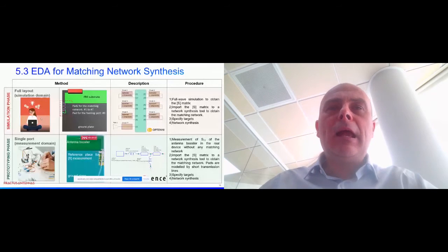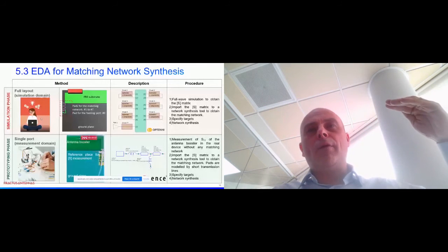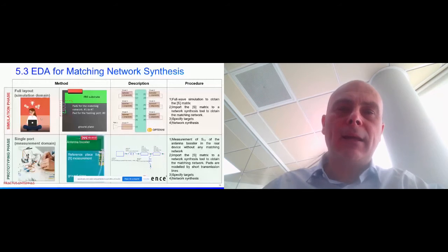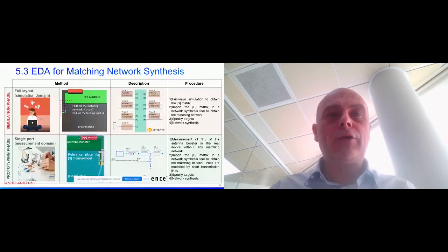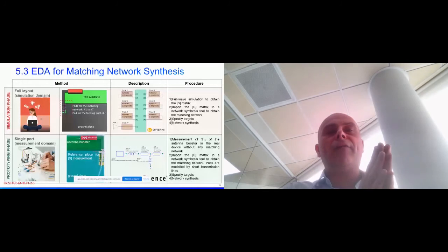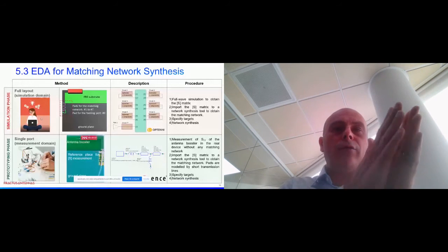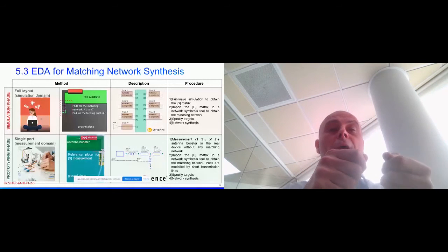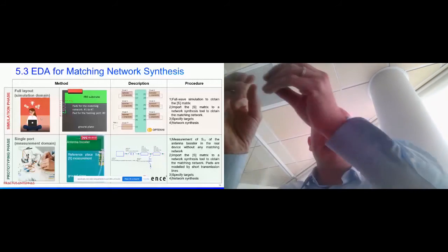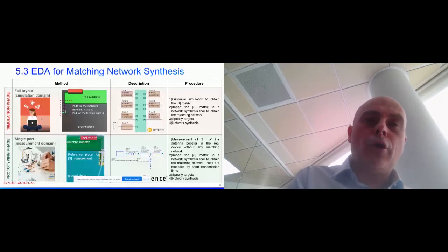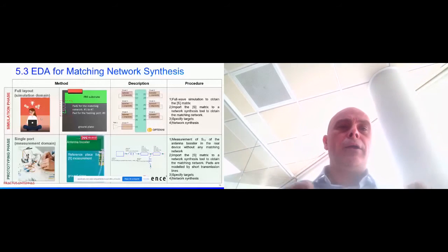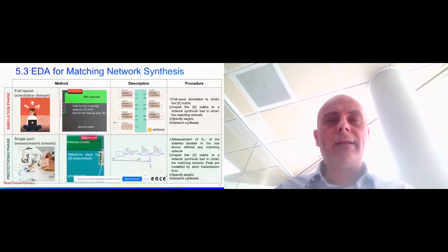We have Optenni, which explains in our webinars step by step how you can design your matching network, or perhaps you are in the lab and you want to optimize the matching network by your own using your own vector network analyzer. So we have materials that explain 1, 2, 3 basic steps that you should do in the lab to do the simulations. And once you get the matching network, just take it and put it on your own PCB, and perhaps with a little fine tuning, but very simple, you have the antenna operating in the frequency band you want.